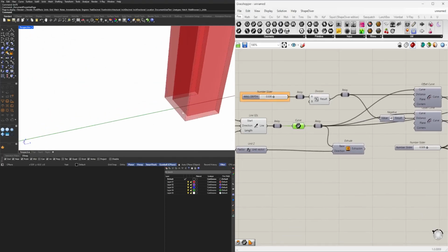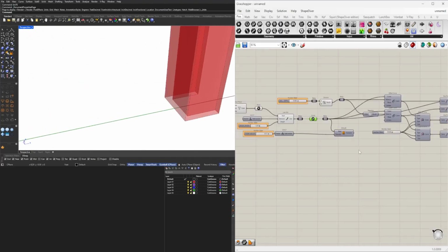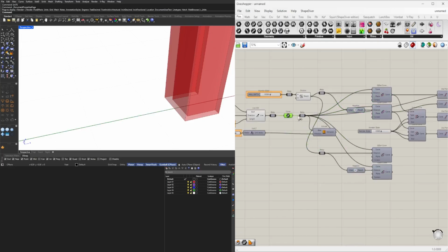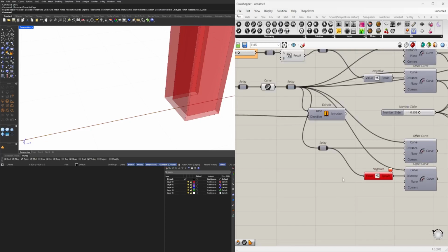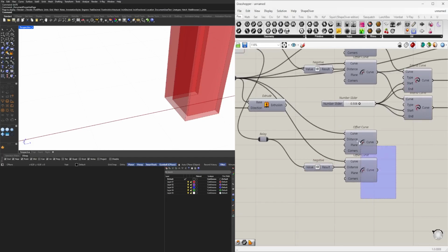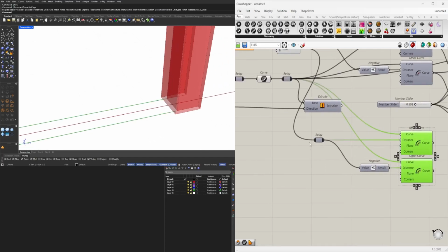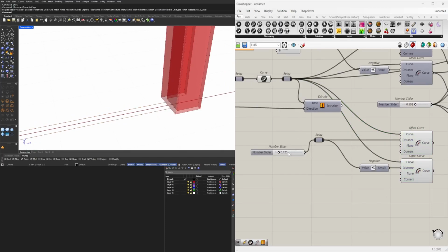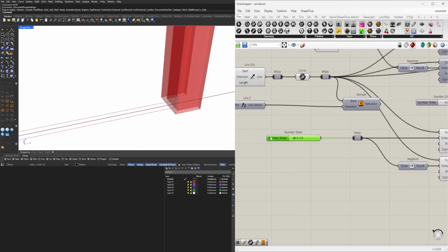If we were to offset this to each side, the same way that we did for the frame, but this time, when I bring this back, you'll see that it's been offset by that much. So we'll do 0.125. And since it's going to both sides, we know that this has to be divided by 2.